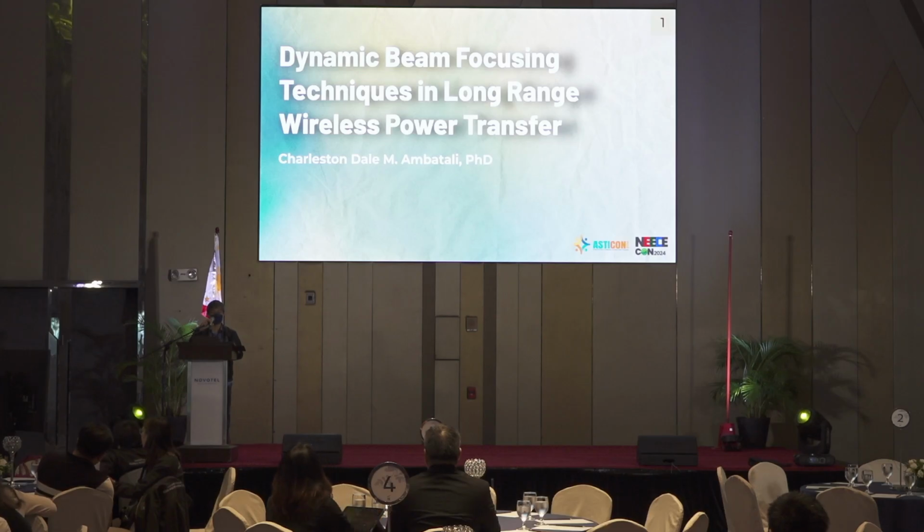First, use of classical beamforming with position tracking sensors. Second, use of pilot signals to train the beamforming antenna. And third, the use of telemetry data as a feedback mechanism. This presentation by Charleston will give an overview, comparison, and contrast of these research works. The analysis of their steady-state wireless power transmission efficiency will also be discussed.